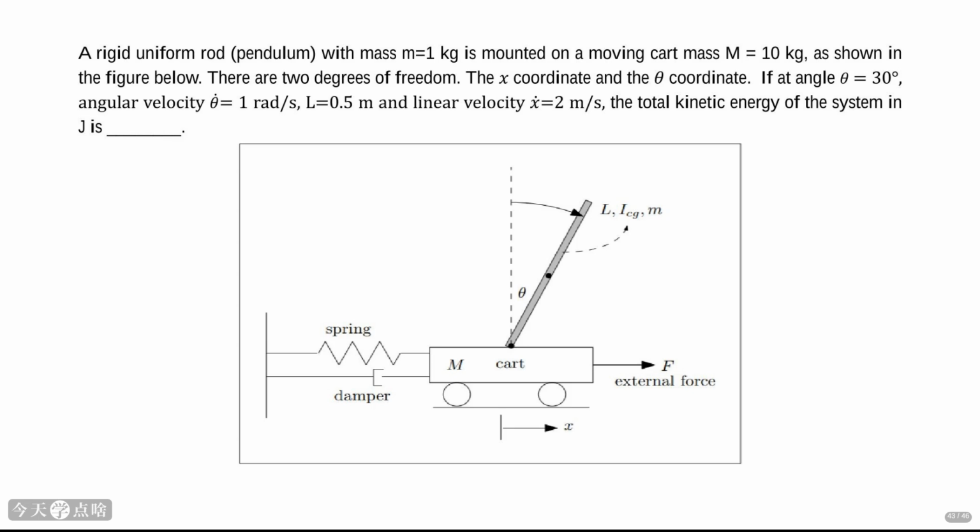You need to consider the kinetic energy of the cart, the kinetic energy of the pendulum's center of mass due to both the cart's motion and its own swing, and the rotational kinetic energy of the pendulum. Let's see if you can work it out.